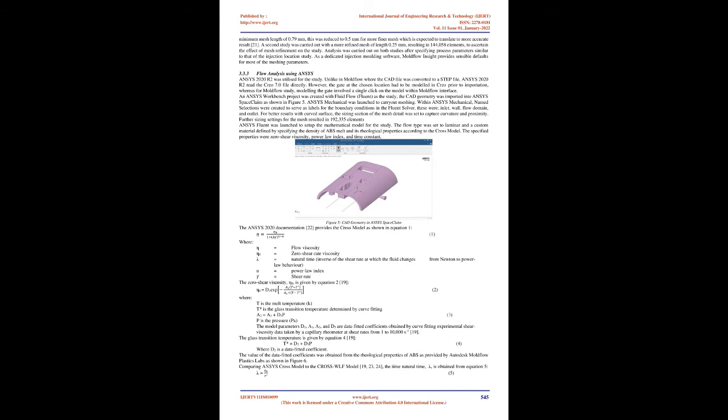Simulation study begins with a CAD model of the part. PTC Creo Parametric 7.0 was used to develop the model of an electric socket adapter top cover. The 3D model captured the details of the part such as openings for plugs and indication lead, screw bosses, and ribs as shown in Figure 2. From the figure, the part has an overall length of 66 mm, width of 48 mm, height of 15 mm, and the wall thickness being 2 mm. Figure 2, three-dimensional model of electric socket adapter.